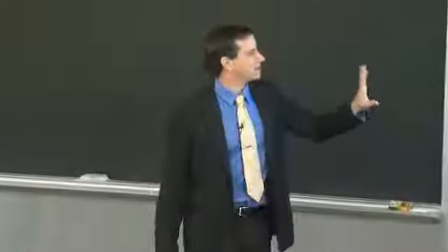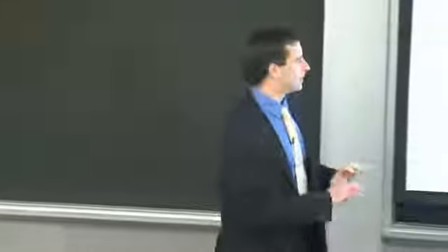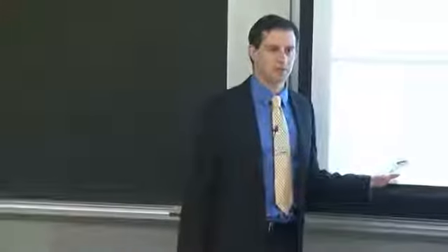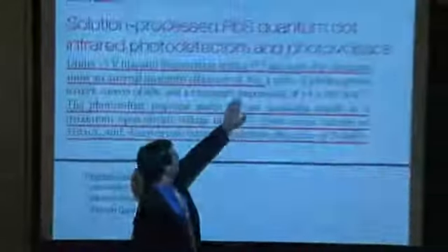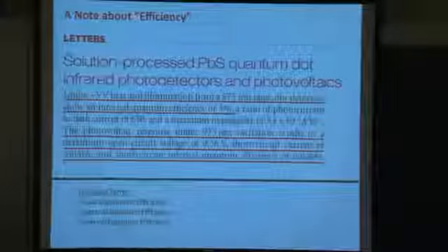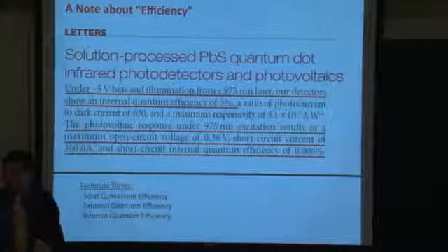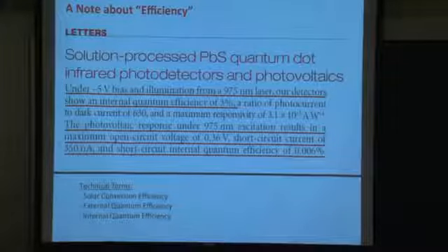So the reason I'm highlighting this abstract right here is because it's a great example of the plethora of different terms that you could find in reading a paper, right? And if you focus on just a few of them, like, 3%, wow, that's awesome, 3% device efficiency. No, it's not energy conversion efficiency. That's the quantum efficiency under a very specific bias condition, reverse bias. It's like a photodetector, not a solar cell, not under forward bias conditions.